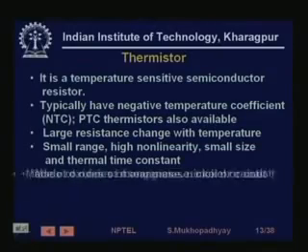Being semiconductor material, it cannot withstand too much temperature. It's also very non-linear. That's a drawback. But it has very small size, and therefore very small thermal inertia, so it can measure very quick temperature fluctuations and can reach various small places. That is what it is used for.